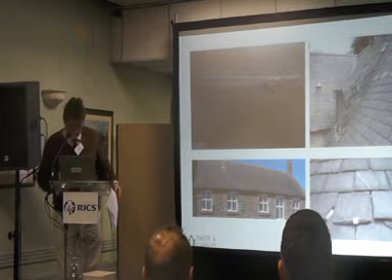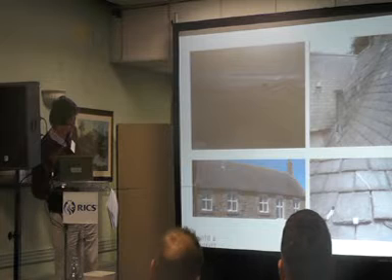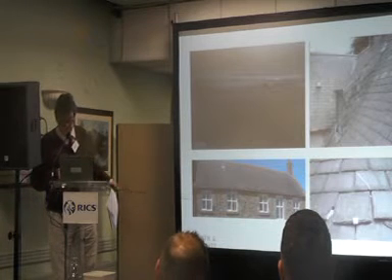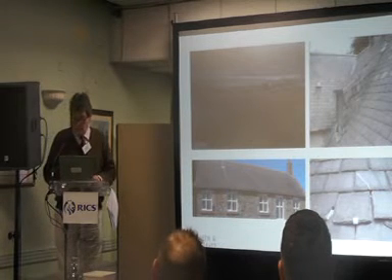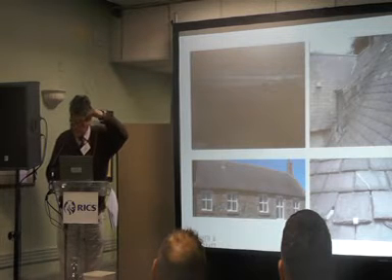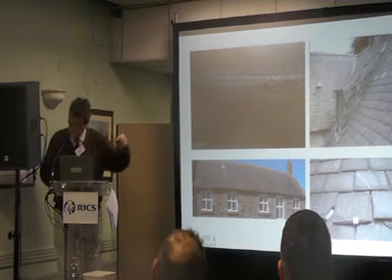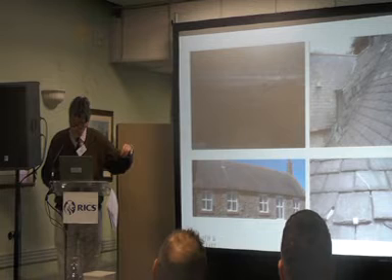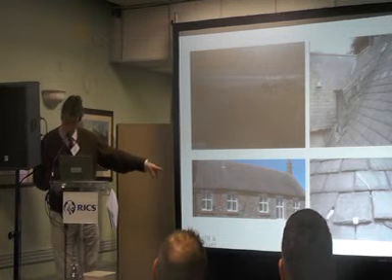This one here, simple problem, no tilting fillet. So you've got two layers of slate coming down a roof, lapped. If you don't put something one slate thick at the bottom, you're going to end up with a weakness just above the gutter.